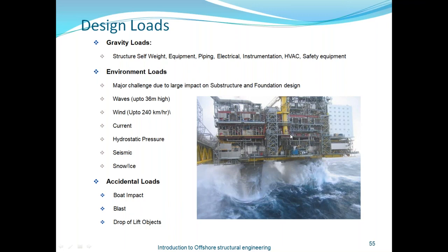The major challenge is to withstand the waves, because all those loads should transfer to the jacket, and from the jacket to the piles. So ultimately your jacket is something like a foundation. Your jacket and piles should withstand all your wave loads. If that is withstanding, then there will be absolutely no problem to the topside structure.